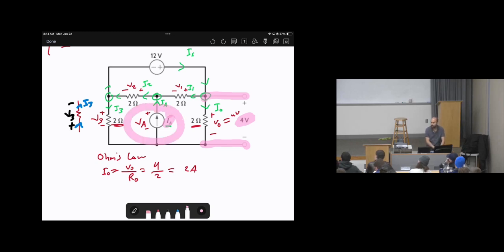We cannot see a V equals I times R. So finding VA will not help me in this. So I need to calculate IA. What other things do I need to calculate? KVL is only used to calculate the voltage. Ohm's law applies where there is a resistor, but this is not a resistor. So I cannot apply KVL or Ohm's law. The only thing that I need to apply is KCL.